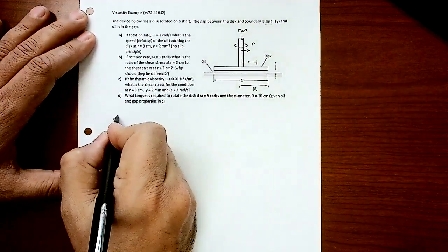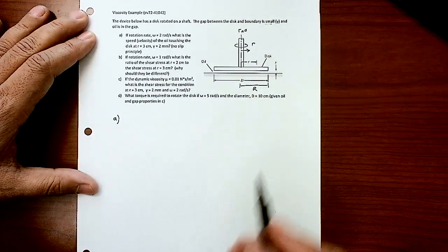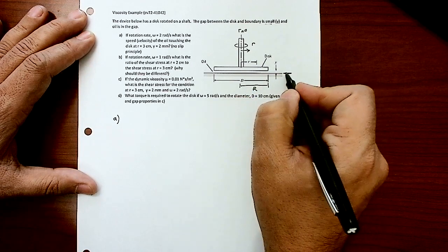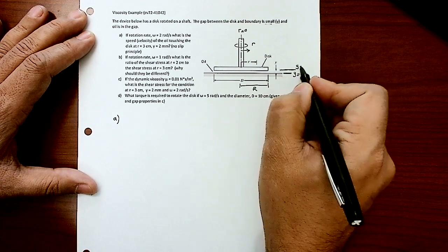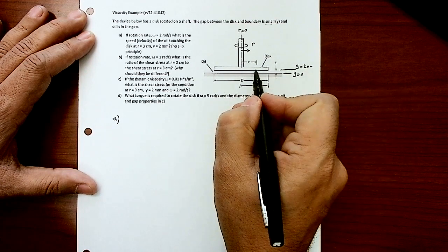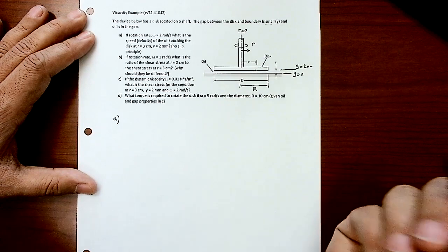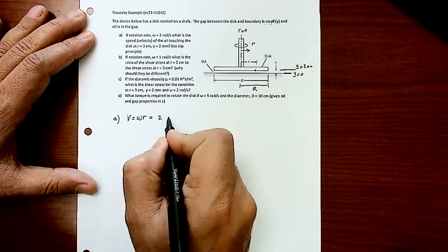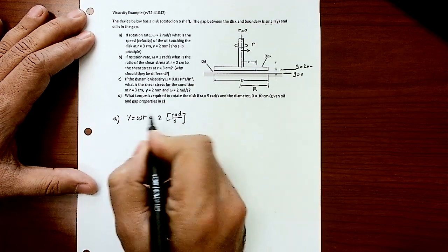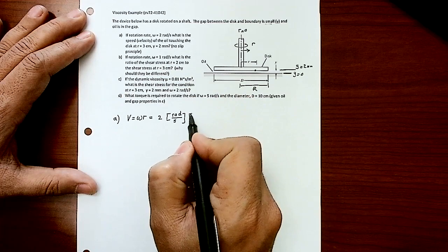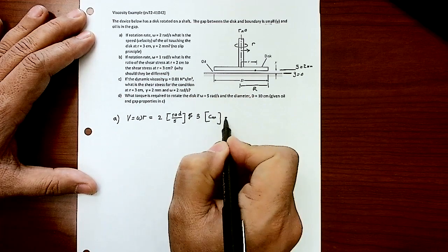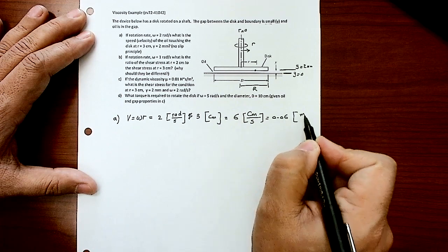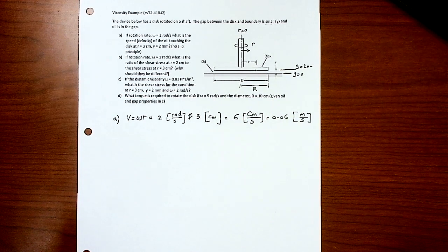So part A is asking to calculate the linear velocity for a point at 3 centimeters away from the center line, and y is measured from here. So this is y equals 0, and the top layer here is y equal to 2 millimeters. Okay, so I need a point actually here that's attached to the rotating disk. What's the linear velocity? We know that linear velocity is equal to the angular velocity times the radius, right? Angular velocity is given by 2 radians per second. And the radius I need to calculate is 3 centimeters. So this will give me 6 centimeters per second. You can convert that into 0.06 meters per second if that's something you prefer. So that's the first part.